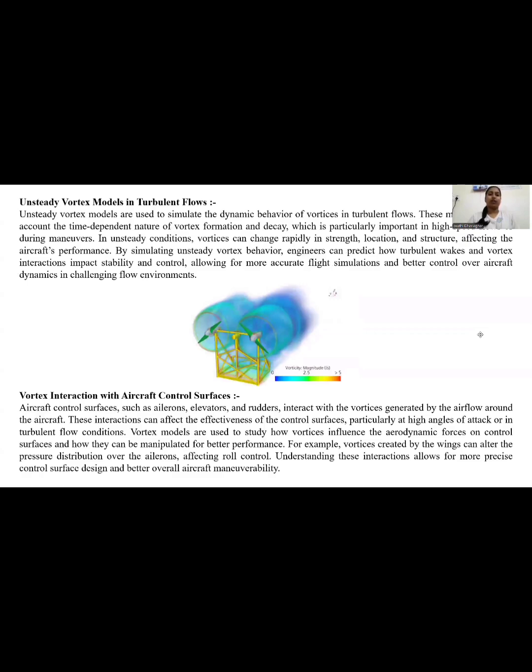Unsteady vortex models are used to simulate the dynamic behavior of vortices in turbulent flow. This model takes into account the time-dependent nature of vortex formation and decay, which are particularly important in high-speed flow or during maneuvers in unsteady conditions.